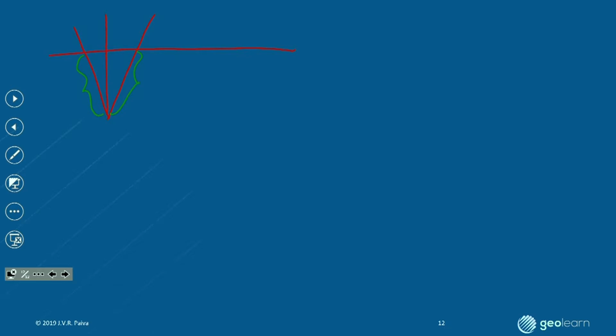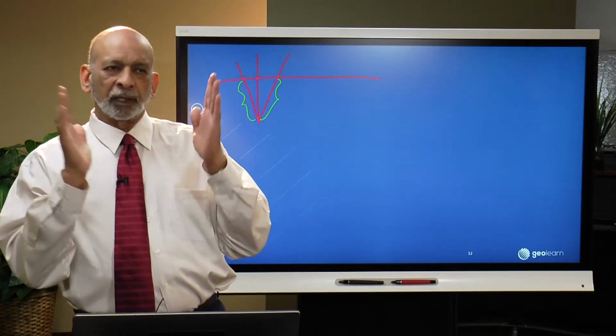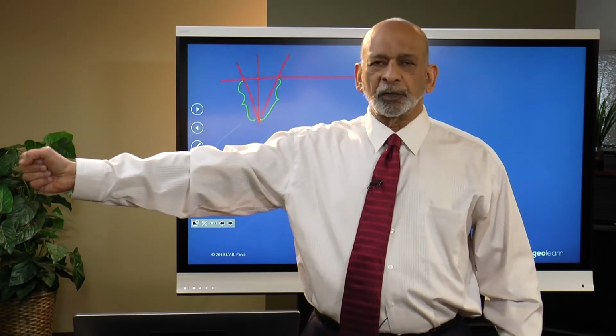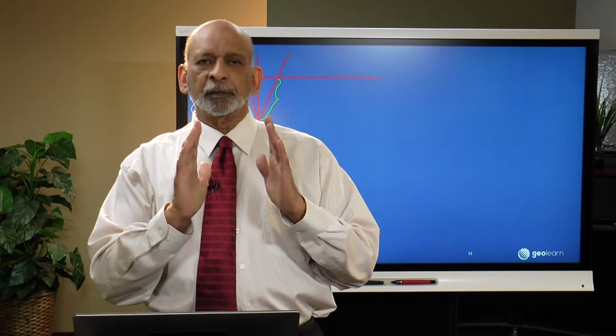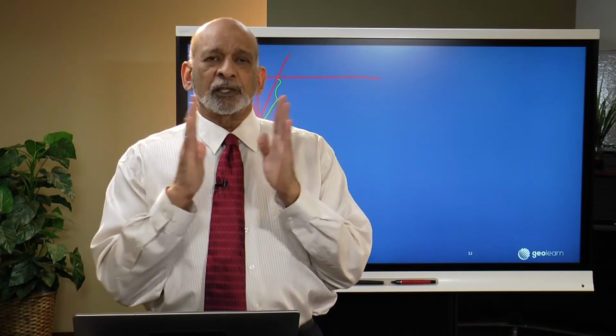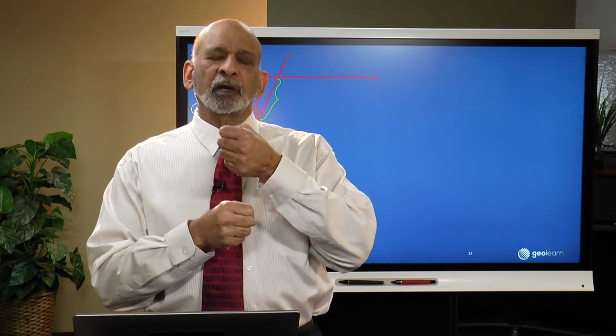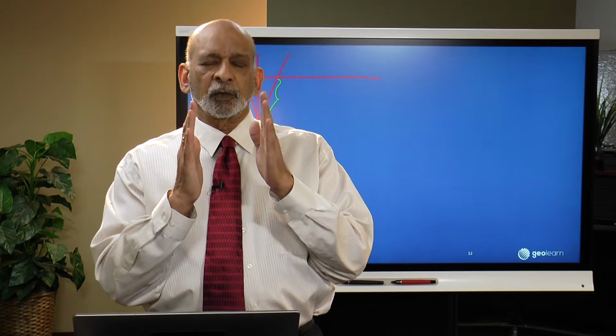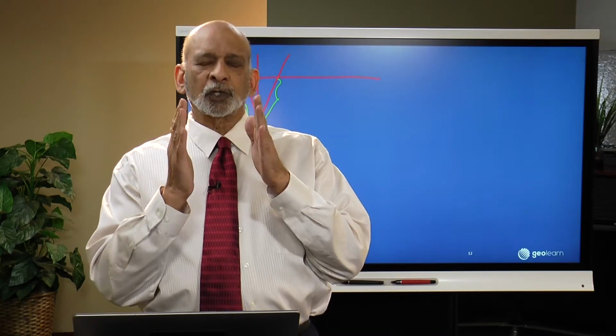One of the things I often suggest to people is stand behind the rod, don't hold the rod off to a side. Always stand behind the rod, feet apart, keep your body straight, and always put your hands on the side of the rod because you don't want to cover up the readings. One of the things you will have read about is that you can do what's called wave the rod.